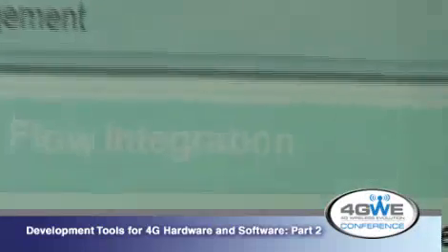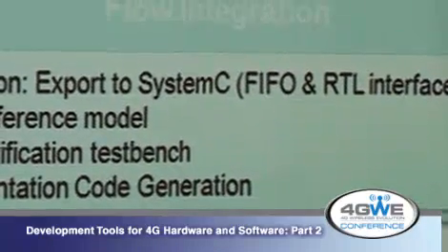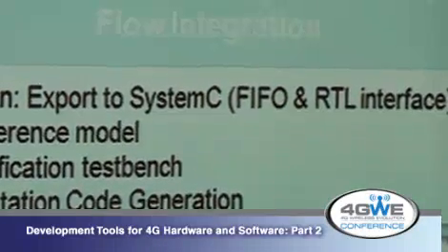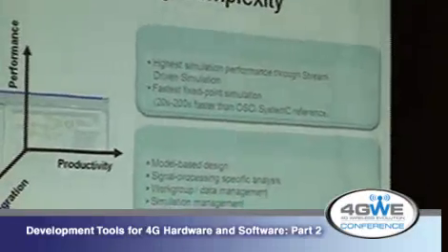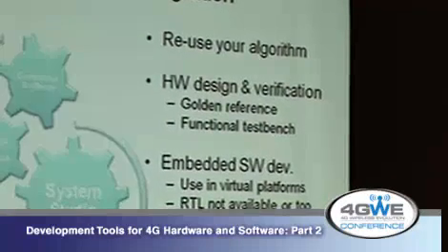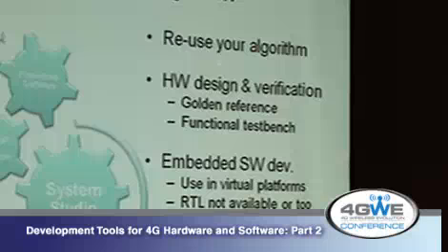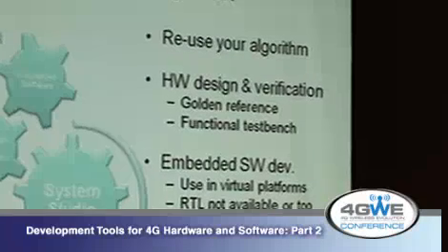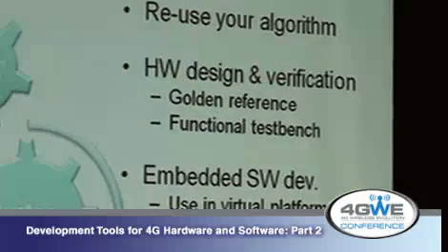The third component is the notion of flow integration. Once I have refined, and this is going back to Chris's slide where he was showing the methodology and the refinement flow from the purely floating point algorithmic model all the way down to RTL, this is essentially the integration I'm referring to. The tools need to be able, from a high level, to connect to verification and even to software development by allowing you to reuse the algorithm work you do at the high level, taking steepest descent libraries, for example.